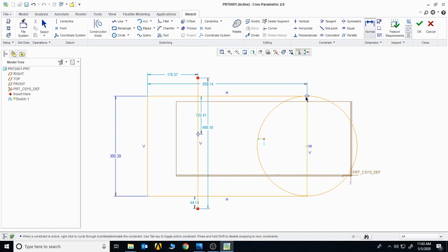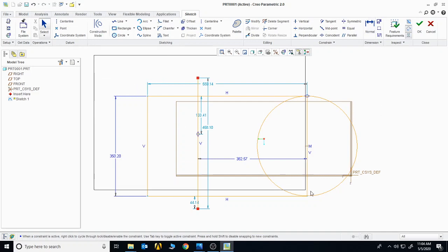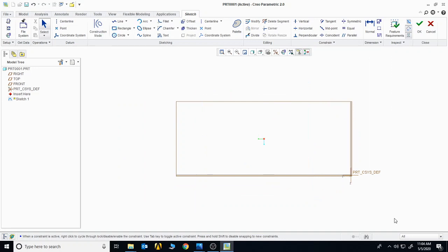Again, let's suppose I want to check the dimensions of this point from this side, so you have to click on the normal, the first side, the second side, and move somewhere there, click on the scroller, so you can see that you have generated your own dimensions. So this is how you can generate the dimensions which aren't given. So this is how dimensions work. In order to delete, select all and click on the delete button.